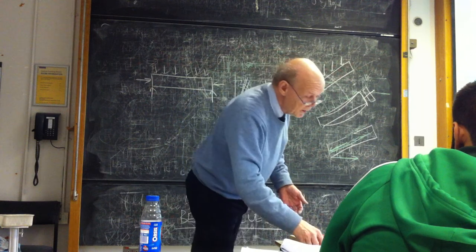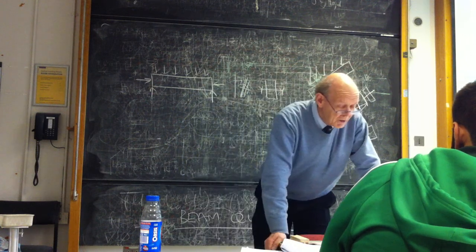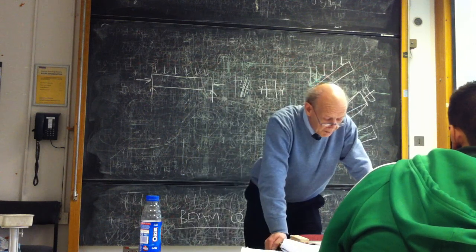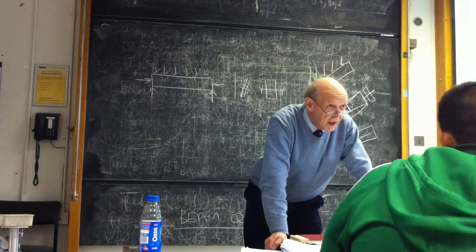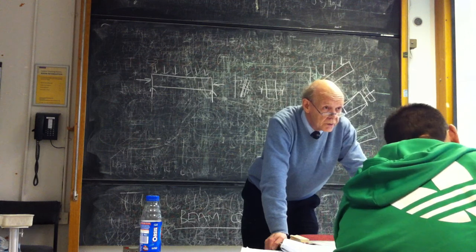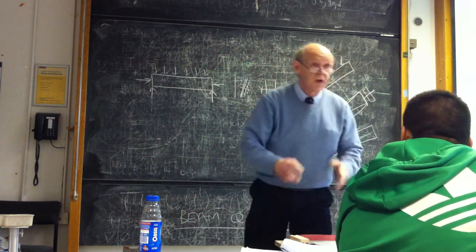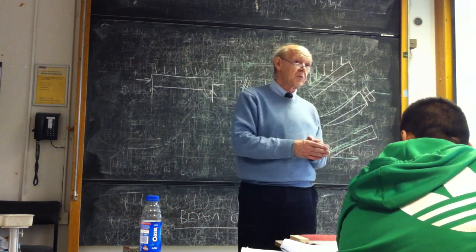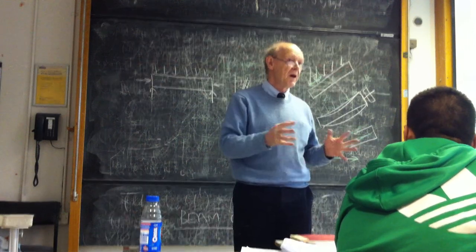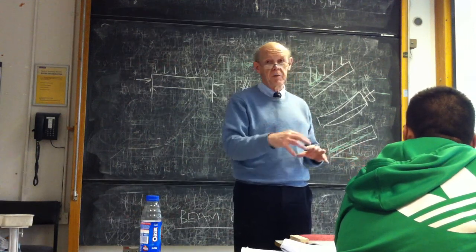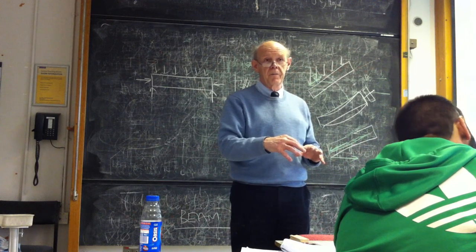So the last one, question 4, is about a 3-pin arch, in which this phenomenon will occur of both bending and quite substantial compressions. But in a lot of the old-fashioned textbooks, they used to refer to it as a beam-column. What they meant by that was it partly behaved like a beam, it partly behaved like a column.